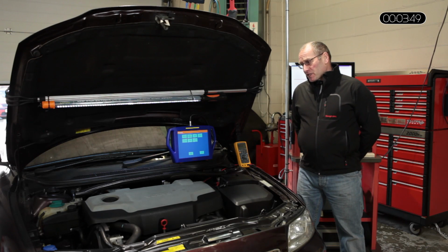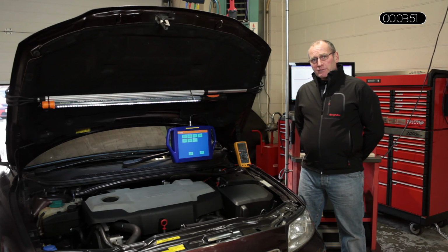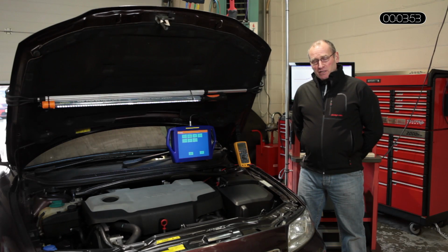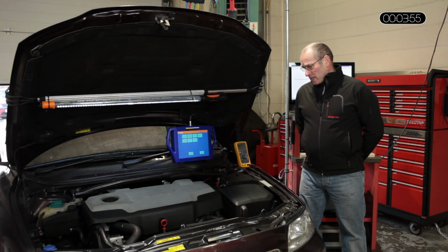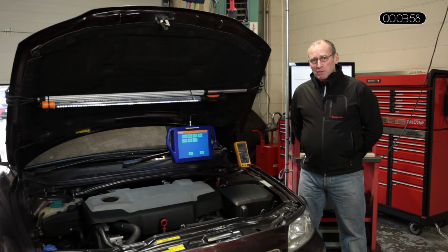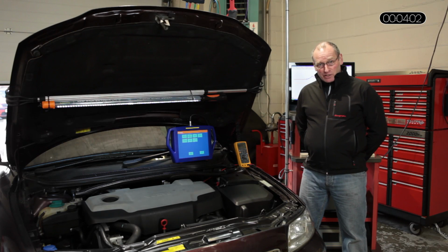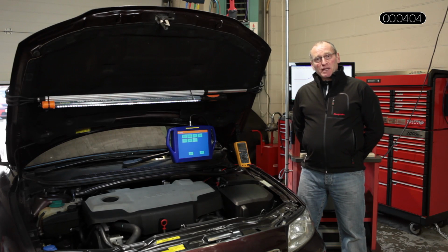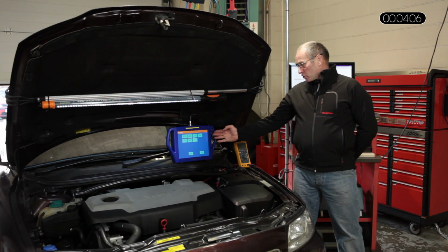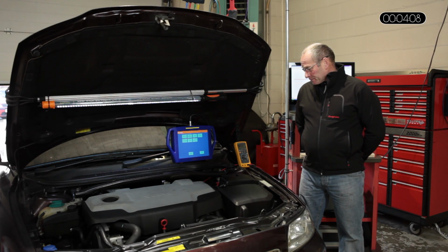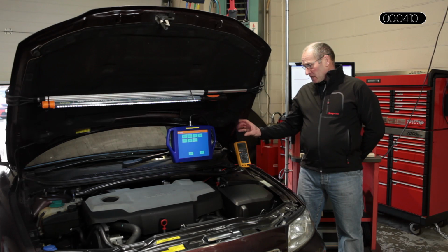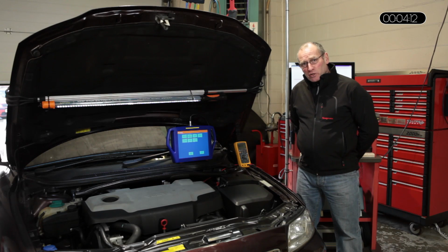That then led us to want to drive the vehicle dynamically on the road, because the logic or the expectation then was that the DPF only became a problem at high engine load conditions, when the volume of exhaust gas was such that the blockage became an issue. So we attached Autologic to the vehicle, and we're going to go through some of this data very shortly. We'll start the engine and go through some of this data.